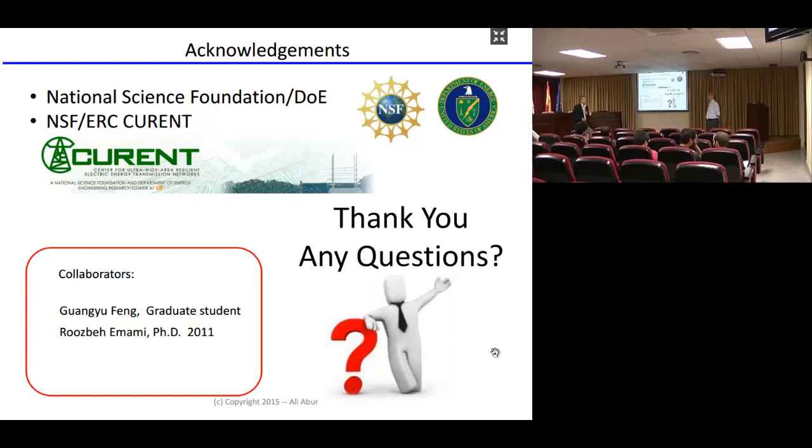Yeah. No, I think we didn't differentiate. It's just the fact that it works, whether it's single phase or multi-phase or mixed phase or all three phase, it doesn't matter. It works. The only thing is, if it's a radial system, the placement of sensors may be an issue, because you don't have that luxury of reaching out from different paths to that point. So you have only one path.